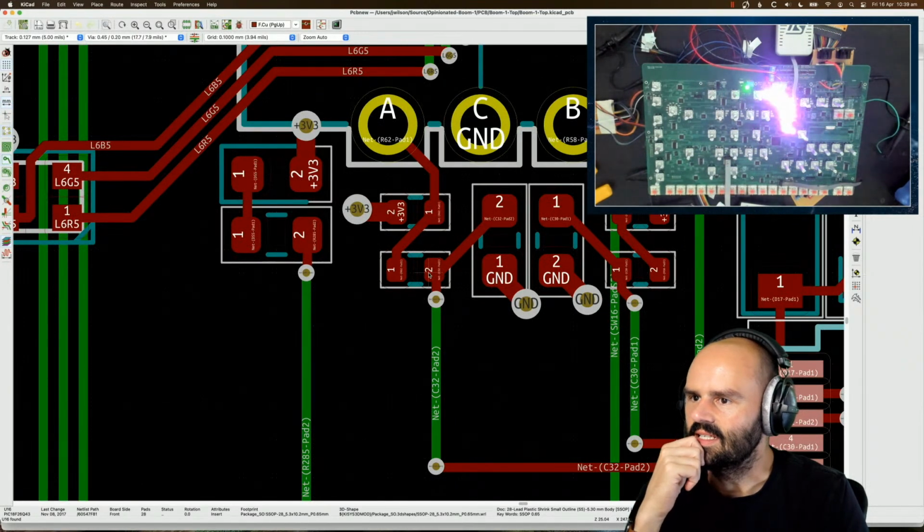But anyway you slice it, when that's crossed, it should drop. If there's no contact, this pin should be high because it's pulled to 3.3. And then if it happens to connect with the ground signal, it's going to pull it down.